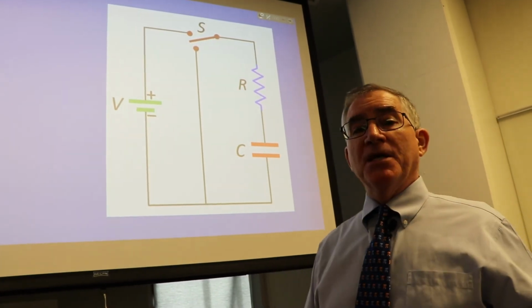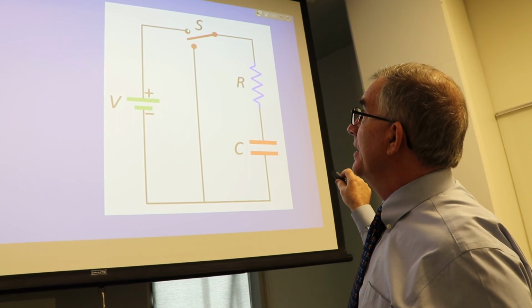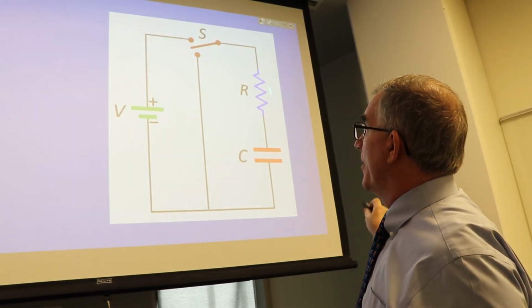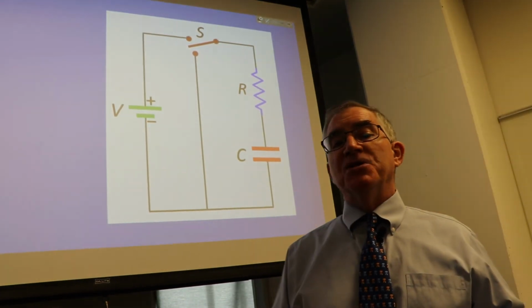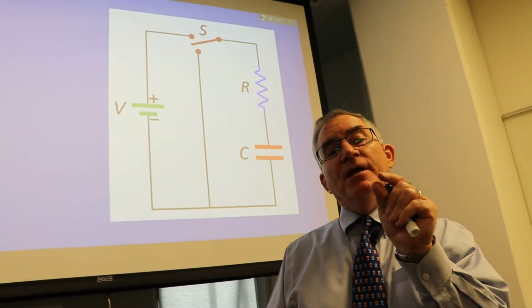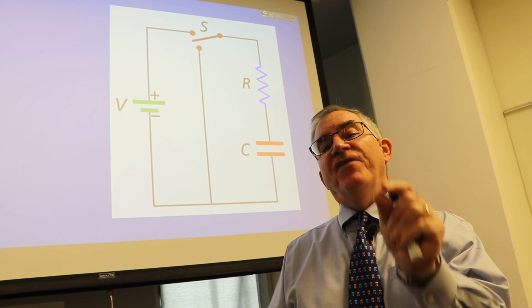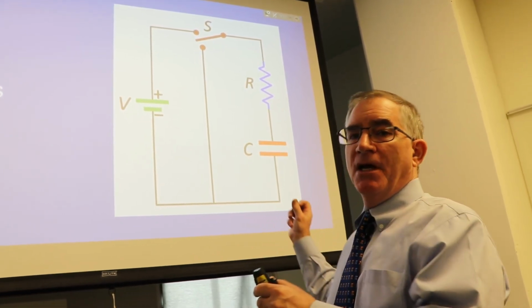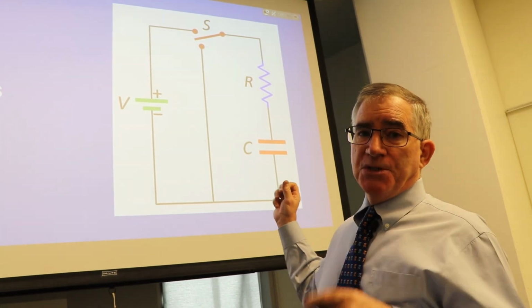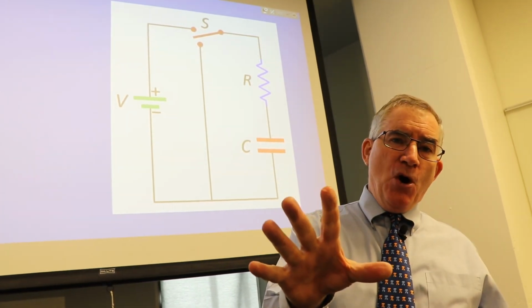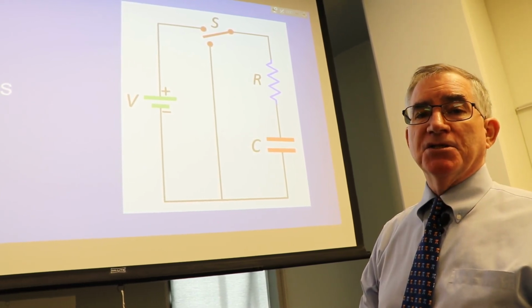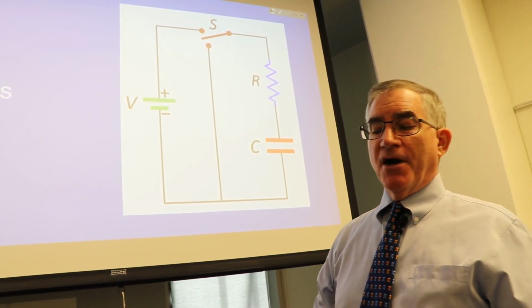Then, when you want to take the picture, you push the little button, and it moves from this position over here to this position. Now remember, the only resistance now is the flash, the little filament inside the light bulb. It's got a very, very low resistance, and that current unloads, the charge unloads, produces max current, boom, right away, and produces that flash and allows you to take pictures when things are dark.